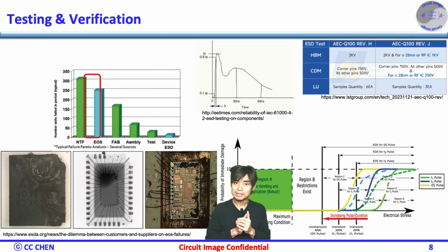Global industry standards dictate minimum ESD protection levels. The JEDEC and IEC standards define test methodologies and pass criteria. JEDEC JESD22-A114 governs HBM testing. JESD22-C101 outlines CDM requirements. Automotive ICs must comply with AEC-Q100, which has strict ESD requirements.